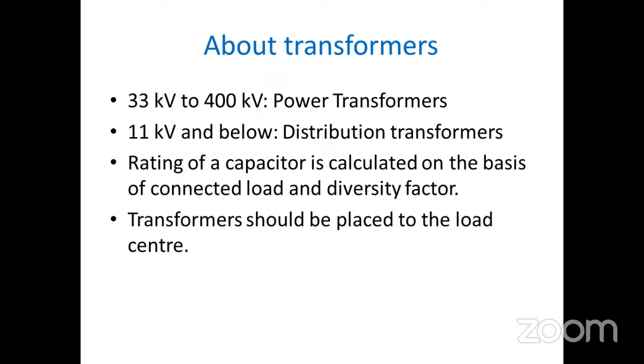If the transformer is placed at the street end, from that street end for that one or 2 kilometers, low voltage line will be going. Once again, the I square R loss problem will come up. So, as far as possible, the transformer should be in the middle. Okay, sir, in the load center.